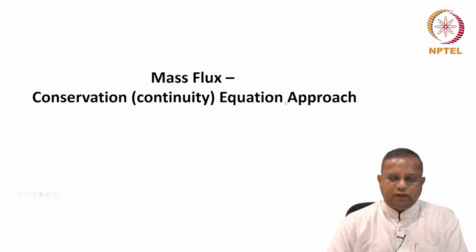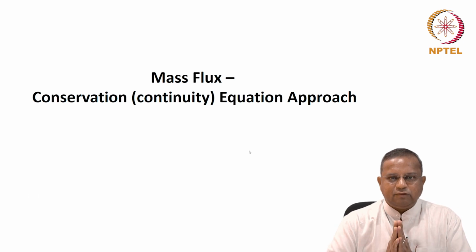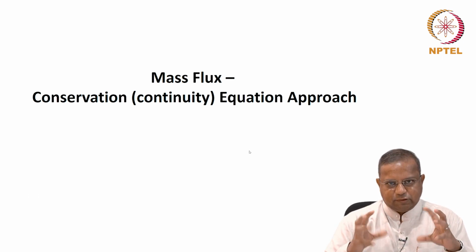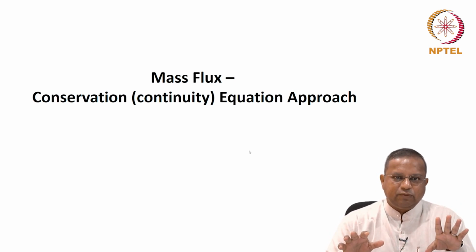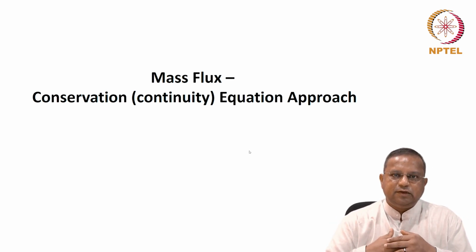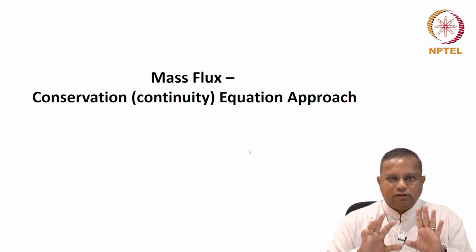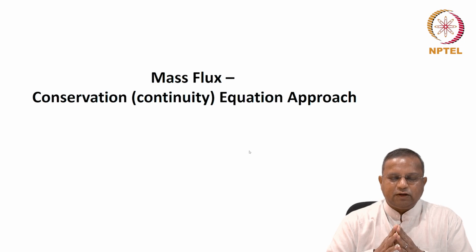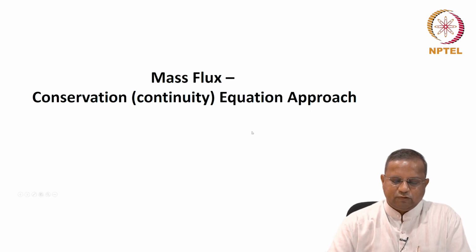Then we looked at the conservation equation approach, or continuity equation approach. We derived the conservation equation because we said shell balances could get cumbersome, especially with cylindrical and spherical coordinate systems. Therefore, we derived a reasonably general equation, one very general equation and another at constant C dAB, which is reasonably general as long as there is no change in geometry. That's one of the limitations. If there is a change in geometry of the system, you cannot use that. Otherwise, you can use that.